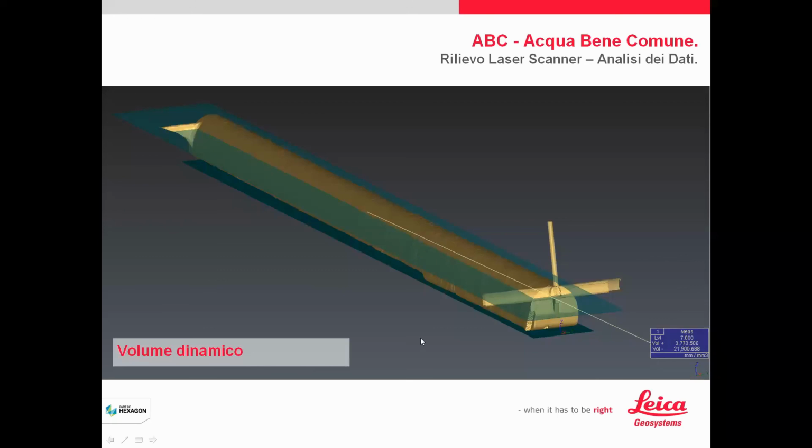This is very important, because they want to know not only how many liters are present when the elevation is 7 meters, but they want to measure exactly, okay, at 5.5 meters, how many liters we have. So with the software, there is the possibility to move the flat plane to elevation 5.5 and then repeat the estimation of the volume. And this is a very, very powerful tool, okay?